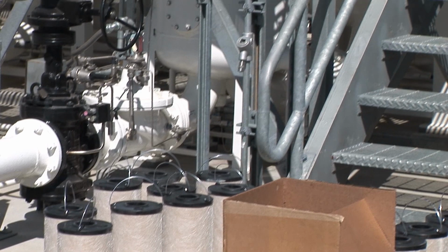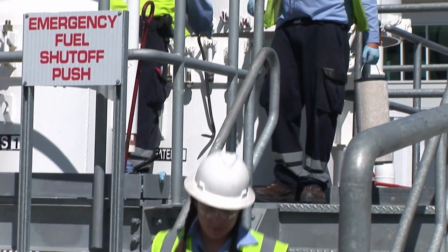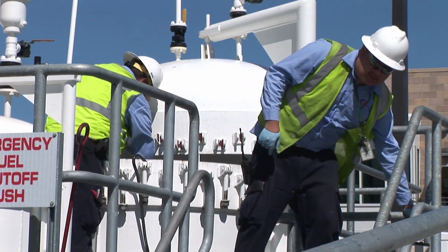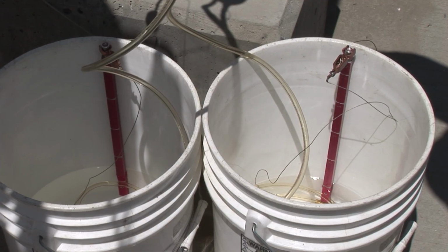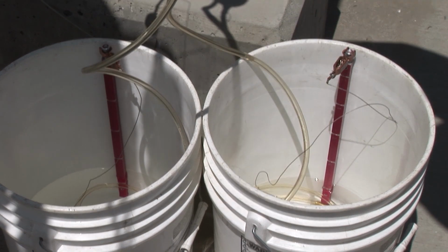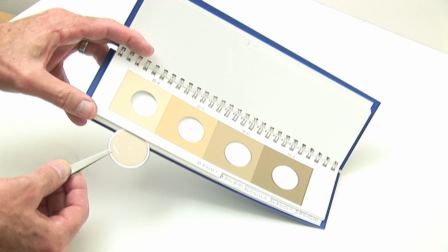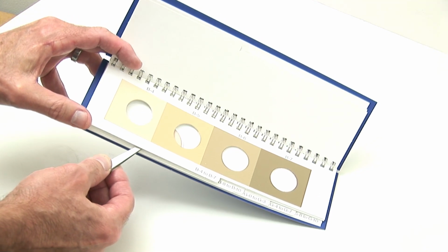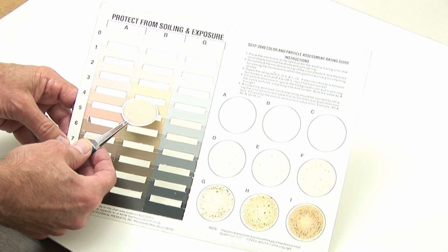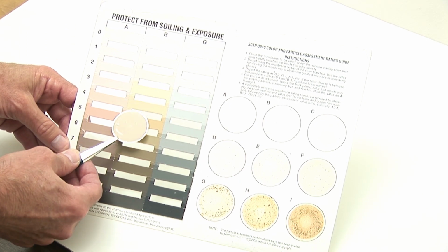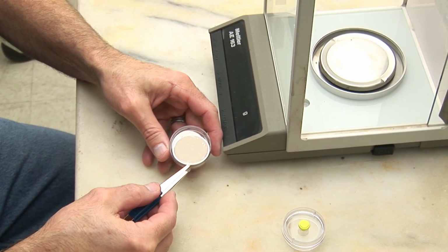There are basic field tests that help you take the guesswork out of when to replace your filter cartridges. The first is membrane field testing. This involves a 1-gallon sampling of fuel through a submicronic membrane. When you compare the color and particulate accumulation against a standard ASTM guide, you'll know the condition of the vessel and elements. To determine the solids concentration, you can perform a gravimetric weight test of each membrane.